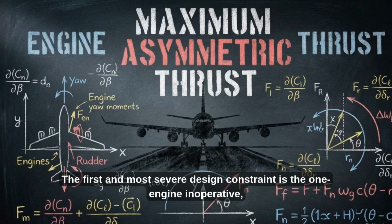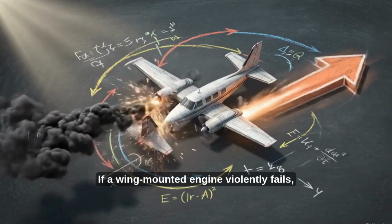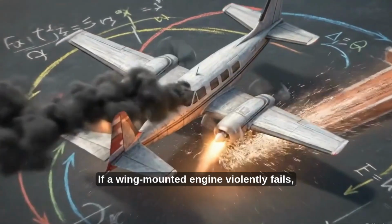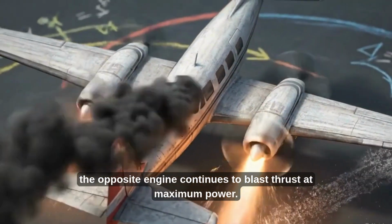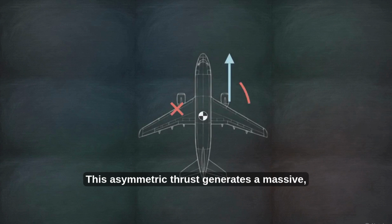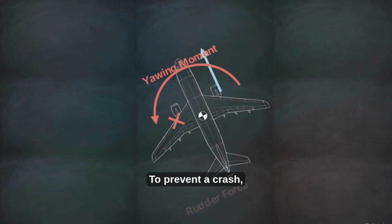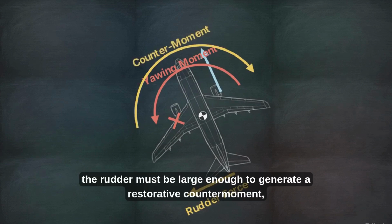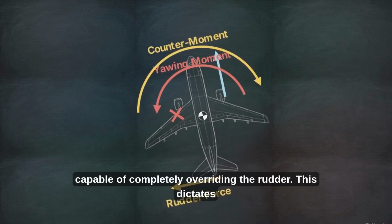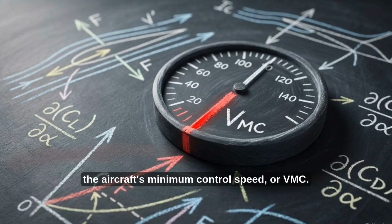The first and most severe design constraint is the one-engine inoperative, or OEI scenario, specifically during a high-power takeoff. If a wing-mounted engine violently fails, the opposite engine continues to blast thrust at maximum power. This asymmetric thrust generates a massive, uncontrolled yawing moment, violently dragging the nose toward the dead engine. To prevent a crash, the rudder must be large enough to generate a restorative countermoment, capable of completely overriding that engine asymmetry. This dictates the aircraft's minimum control speed, or VMC.